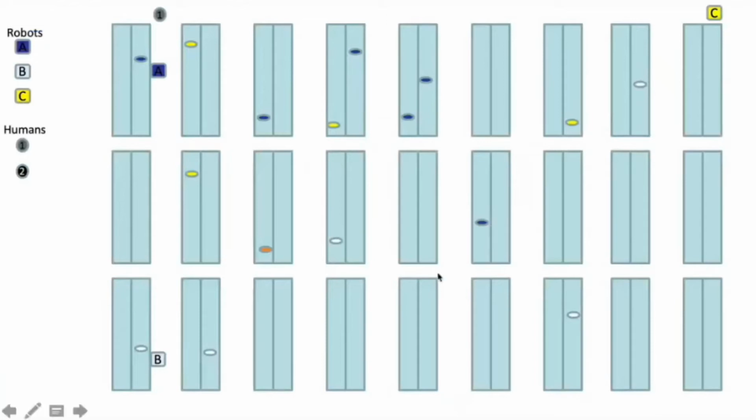So here a picker is directed to pick location and robot A. Once the first pick is completed, the system takes into consideration the location of the picker as well as the location of all the picks and the corresponding robots. The system directs the picker to the location directly behind them and coordinates moving the correct robot to that location, and also positions robots for future picks. Once that pick is completed, the system directs the picker and the robot to the next pick location.